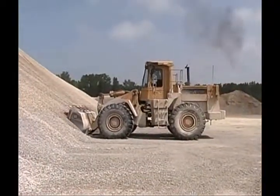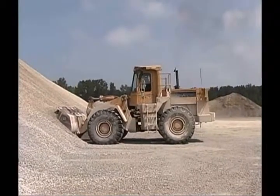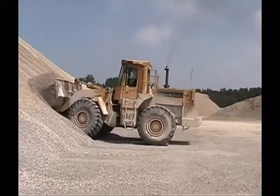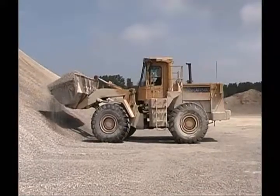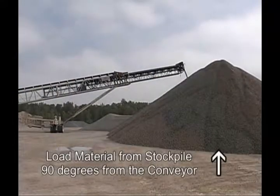Loaders should not scrape the quarry floor when loading material, but should raise the bucket slightly when entering the pile and continue raising the bucket throughout the stockpile. Material should be loaded from the stockpile at a 90-degree angle to the conveyor belt, working the entire stockpile from side to side. This procedure also aids in blending segregated material.